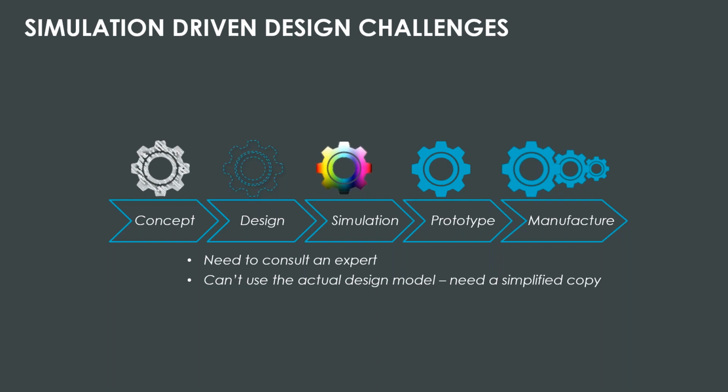Initial task, more often than not, is to figure out how to simplify a copy of the model, right? So that's typically what happens. They cannot use the design model that the engineer is providing. They may have to create a simplified copy so it can mesh quickly. And ultimately, the goal is to have the simulation run in reasonable time, but still provide an actionable answer. And typically, engineers don't feel comfortable making that judgment, right? And these are some of the barriers, right?